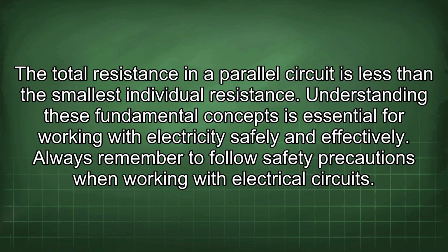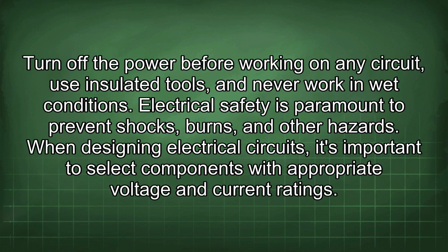Understanding these fundamental concepts is essential for working with electricity safely and effectively. Always remember to follow safety precautions when working with electrical circuits. Turn off the power before working on any circuit, use insulated tools, and never work in wet conditions. Electrical safety is paramount to prevent shocks, burns, and other hazards.